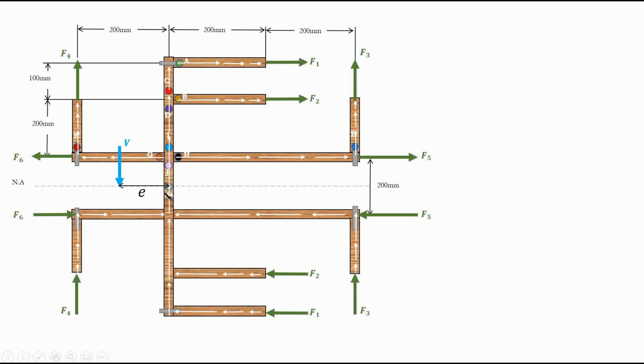So we say, okay, there's a distance from this web to the location where I apply my shear force, where my twist will be 0. That's what we're trying to find. So just take the moment about any point. In this case, we're going to take the moment about the web. The reason is that, if you remember, we found F1, F2, F3, F5, but there's also a force, a very large force in fact, in the web, right? There's a very large force upward in this web member.